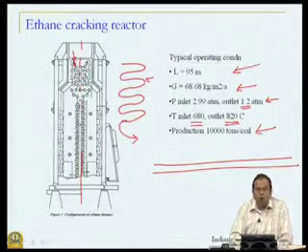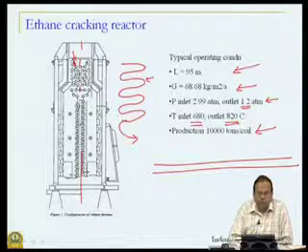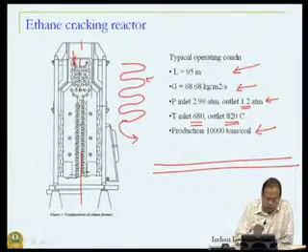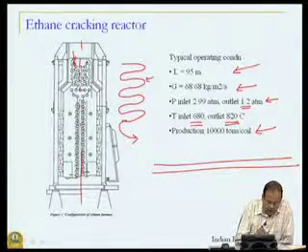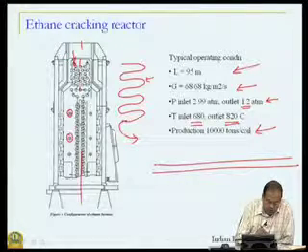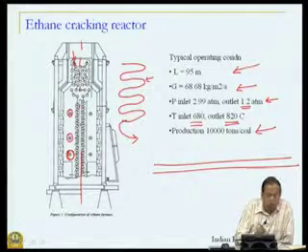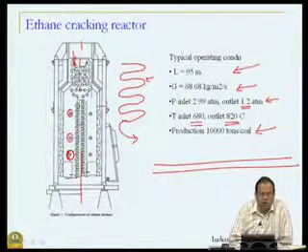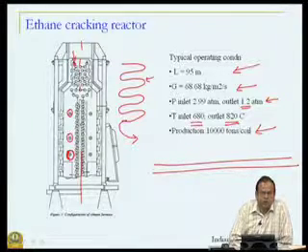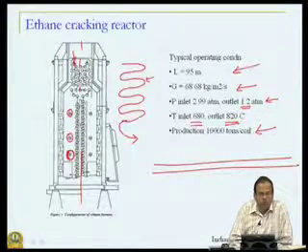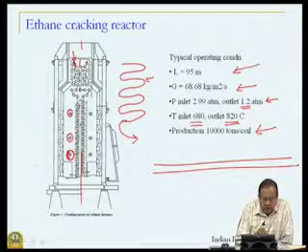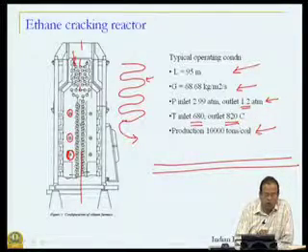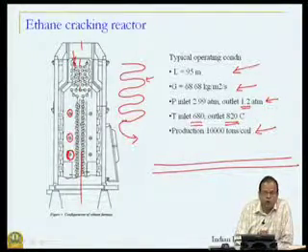Now, you also want fairly high temperatures. So, how do we achieve that? On the sides, what you see here are actually flue gas burners, and therefore, these are what are called furnaces. So, you are burning flue gases, or passing hot flue gases, through the external of these coils, thereby achieving two things.